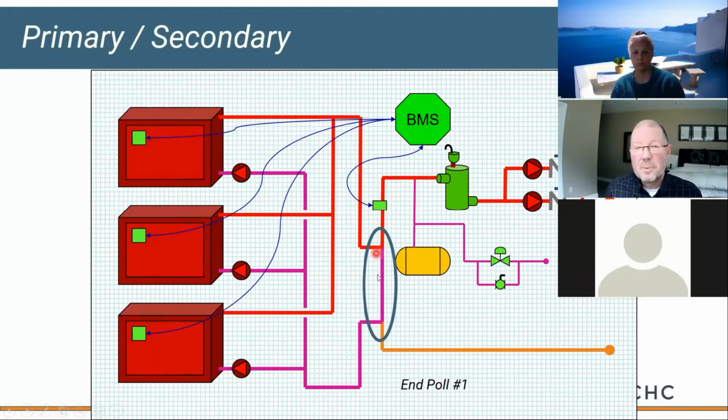So Bridget, forgive me, I'm not sure I'm answering your question directly, but there's a number of variables to consider when you're in design. If it's going to affect your system greatly, then either put a dedicated pump on here that might be constant speed, or feel free to make it variable speed. A lot of times boilers will have an output signal as they modulate their burner to control a pump.